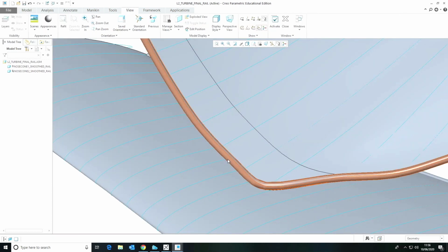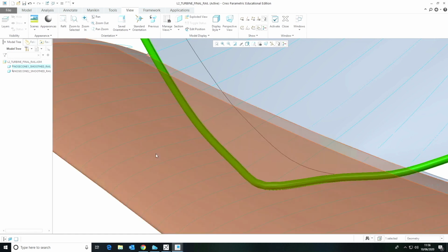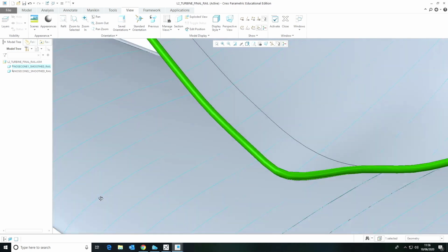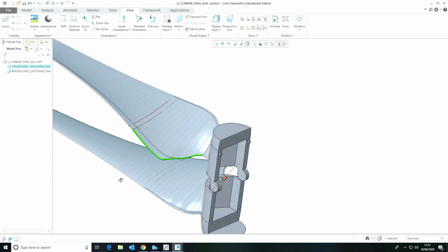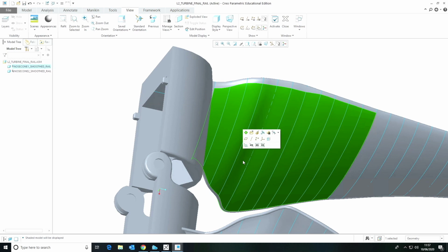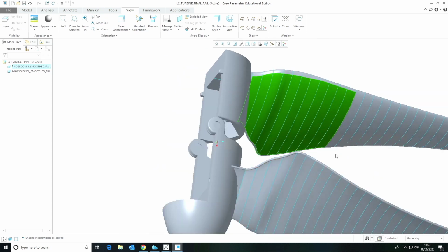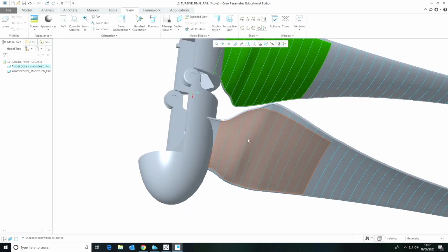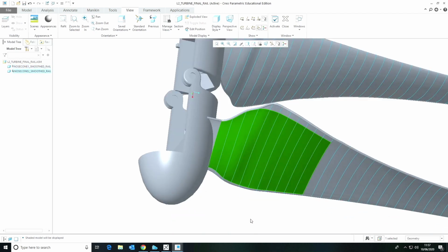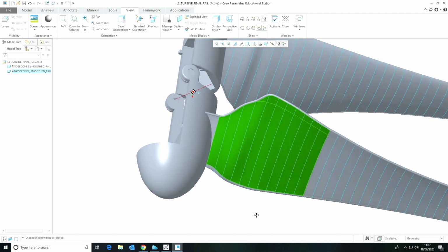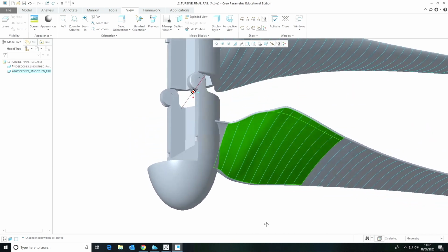There was some worry that the 3D print would be unable to capture the most thin parts of the aerofoil. Therefore, the rail helped provide an outline of the trailing edge for the print to aim for. As our design used two different aerofoils, they had to be blended together. Although stall was accounted for in the calculations of the twist angles, there was still some worry that in practice the aerofoils may suddenly stall at different points, and therefore produce unanticipated loads on the blade. To try and mitigate this, small bumps analogous to whale tubercles were incorporated into the region of transition between the two aerofoils, as seen here. A further discussion on the aerodynamic advantages of these features is provided later on.